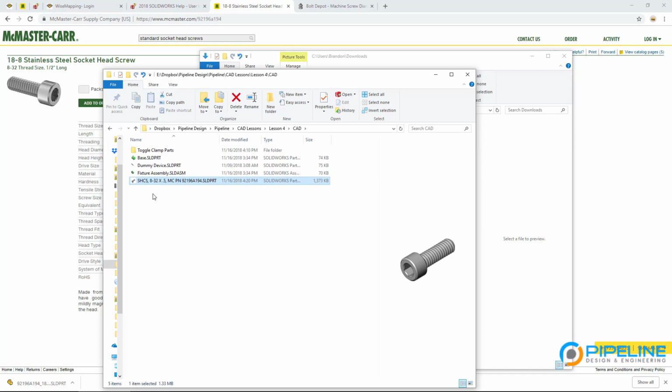But it's possible in the future you decide to clean up your download folder and you delete everything from there, and you don't realize that the assembly somewhere else on your hard drive is looking at that file. The next time you open up the assembly, it'll look in your download folder and it won't find the part, so the assembly won't be able to load that information. It'll give you a big error, and that part won't load in the assembly. You could avoid these types of headaches by just always keeping all of the relevant parts to an assembly in the same directory until you're given a reason otherwise.